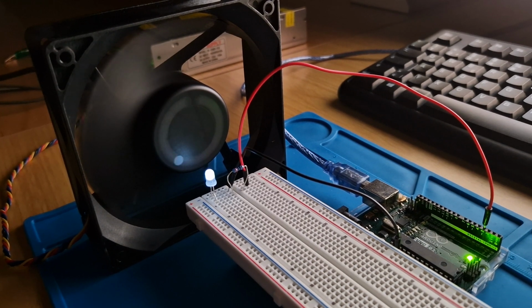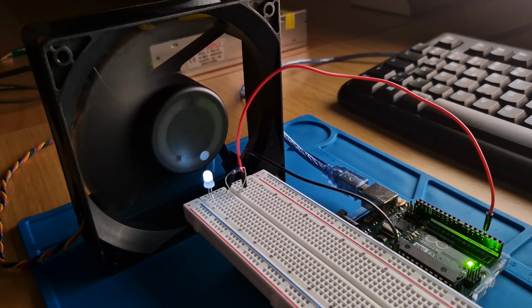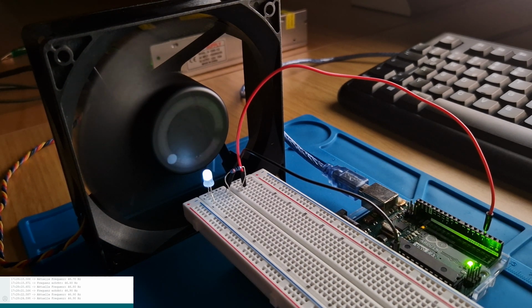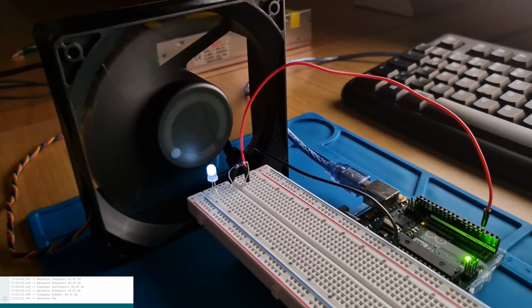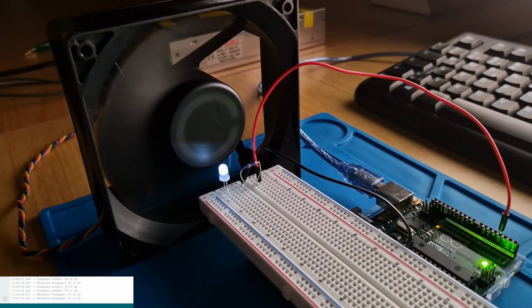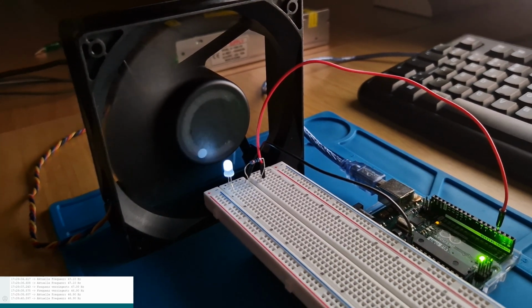You can see the marker moves slowly. I use the plus key on the keyboard to increase the blinking frequency. The marker stops at approximately 14.68 or 14.69 Hz. This means that the air fan is rotating at 14.69 Hz or 2814 revolutions per minute. Now I am trying to double the blinking frequency to see 2 marker points.